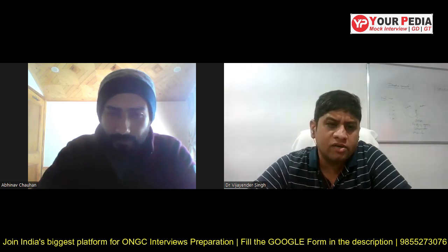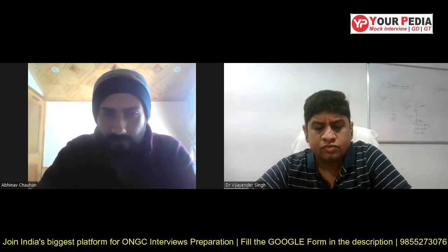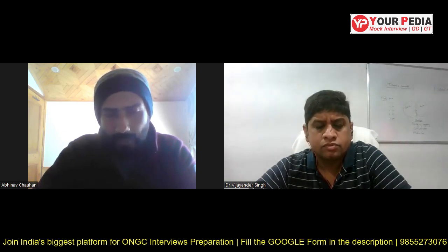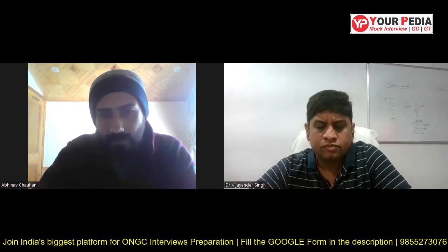Can you tell me some of the dimensionless numbers which you use while modeling of turbines? Yes, sir. So we use Euler's number, which is the ratio of pressure force upon inertia force. We have a Reynolds number, which is inertia force upon viscous force. And then we have a Weber number, which is inertia force upon surface tension forces, and Mach number, which is V upon C, and one more, Froude number, inertia upon gravity forces.